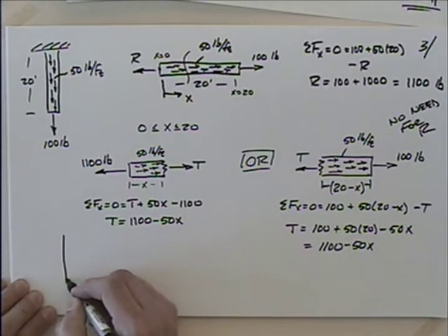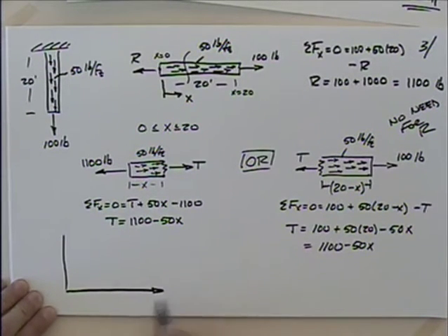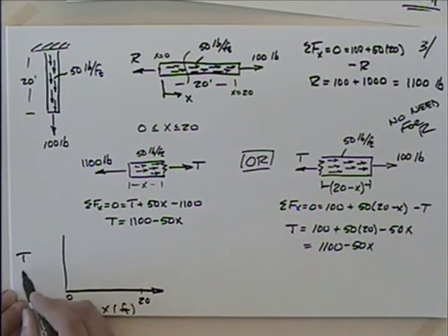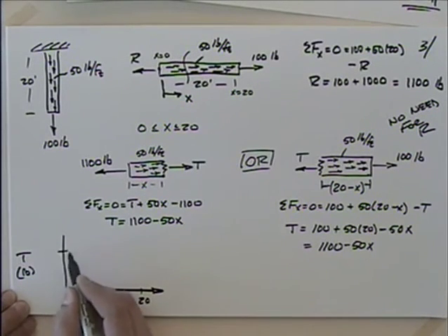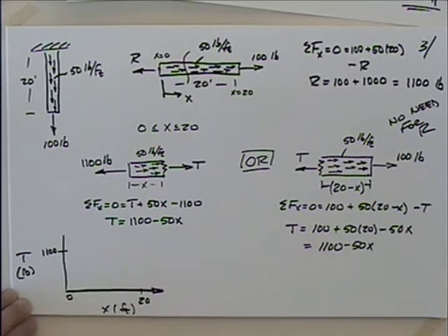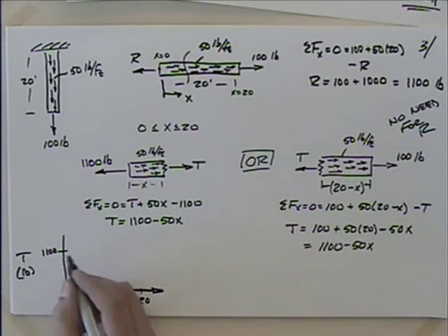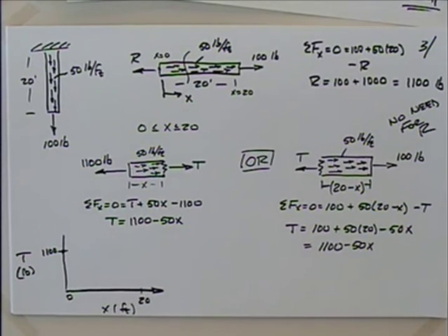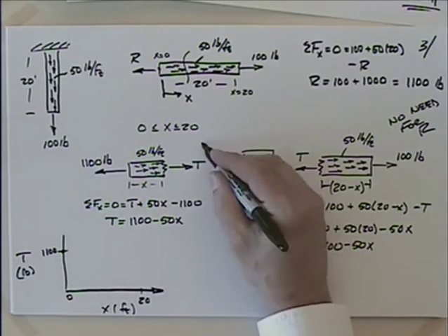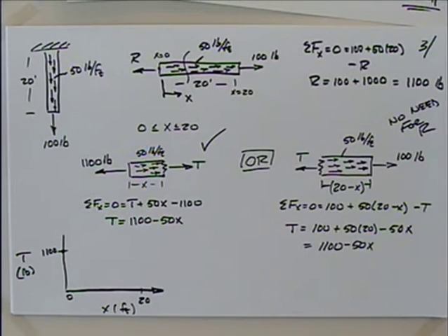draw the picture, here is x in feet, 0, 20, and then we have the t in pounds. When it's at 0, we're going to be at what, 1100? Having found that reaction to be 1100, that number is quite a bit more satisfying, right? If I didn't know that, I'd probably be a little more worried. But since I know the reaction is 1100, I like it that that equation hits there. So I don't think there is anything wrong with doing it this way. Finding that reaction is kind of a nice check through this process.